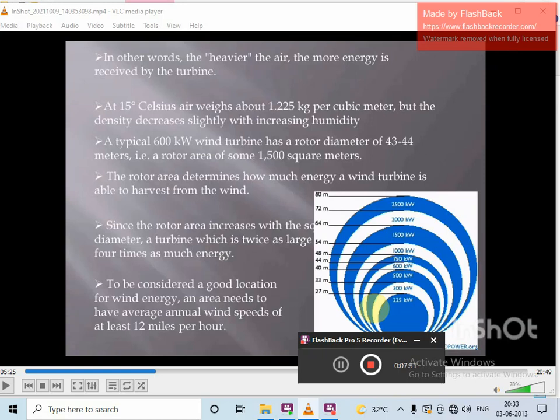And one more commonly used statistical method regarding the wind speed is the Weibull distribution. The variation of wind speed for a particular site can be described by using the Weibull distribution function. So the Weibull distribution function involves a scaling factor, and the actual wind speed can be predicted from that formula. Again, there you also need to feed the observed wind speed data. So from that, using the PDF function, you can predict the wind speed.